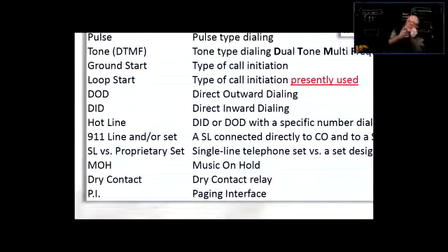What happens is that if that amplifier is connected all the time to those speakers, and if nothing is connected to the input, and the input is not grounded or shut down, then we would have a problem with noises coming through the speakers, like white noise or pink noise, a hiss or buzz or something. So that input has to be shut down when it's not used, and it only has to be opened when it's used.